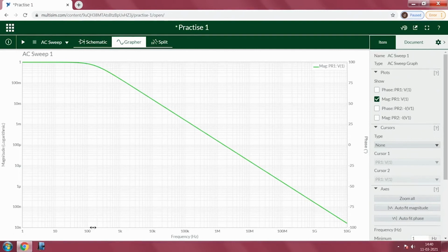So, in order to understand the cutoff frequency, you can plot the 3 dB. Since it is 1, the value 3 dB lesser than that will be the cutoff, so the cutoff frequency will be close to, so this is 1, so this will be 700 approximately. So, it is around 125.89 Hz as the cutoff frequency. If you want to see the cutoff frequency 1 by 2 pi RC, just analyze that and match it with the cutoff frequency.